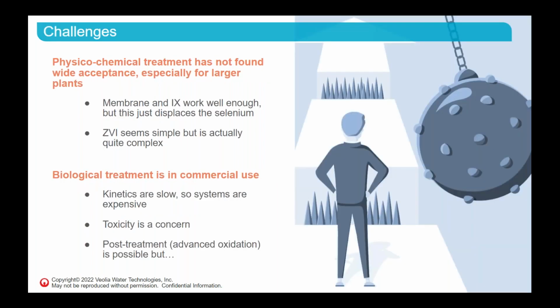Now, the issues. Physico-chemical treatment has not found wide acceptance, and there's a reason for that. Basically, membrane and ion exchange, they work, but you just displace the selenium. So basically, you do produce a concentrate, and then you have the same amount of selenium that you had before.